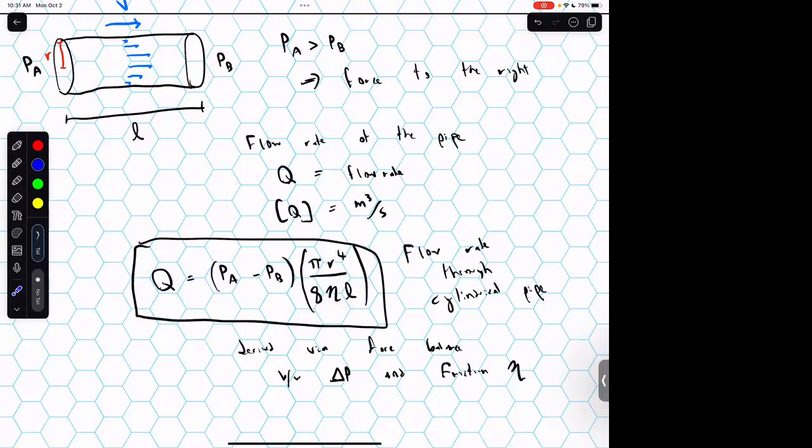And then the other thing that makes sense here is that there's viscosity in the denominator. So big viscosity has low flow rate. That makes sense because presumably if I'm trying to pump, I don't know, maple syrup out of the maple syrup factory, that's going to be a lot more expensive and difficult than something like water. In fact, a big thing that people in petroleum engineering study is whether you can add things to oil to basically lower its effective viscosity. So people dump polymers and all sorts of weird stuff into oil just in order to make this equation maximize this.